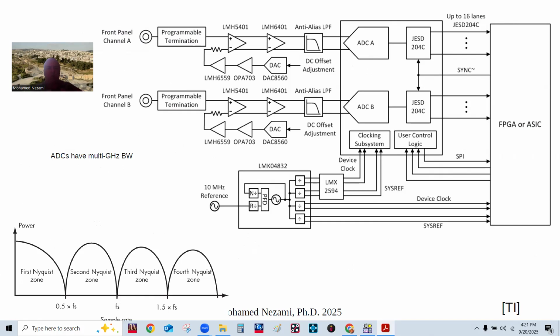This could very much be the signal from an antenna that has been amplified through a low noise amplifier, through some preselectors, and fed directly into this, because these ADCs are gigasamples per second. But this shows you how this differential amplification is done for a sensor signal. And even this one uses a programmable DC offset, because you can steer this, optimize, and keep track of the signal so that you always try to center it into the ADC capture range.